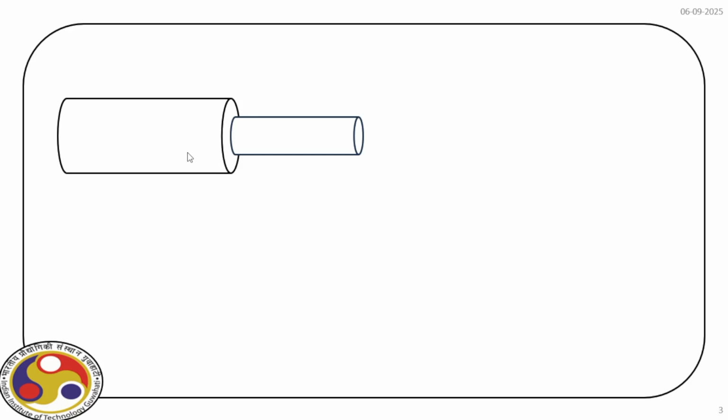Actually, this kind of variation in cross section of a shaft we often see in mechanical devices, and that's the reason. Let us see how we can solve this problem. But before that, if you recall, the expression we derived for a circular shaft is phi is equal to T times L divided by G times Ip. Right? Now, non-uniform bars.